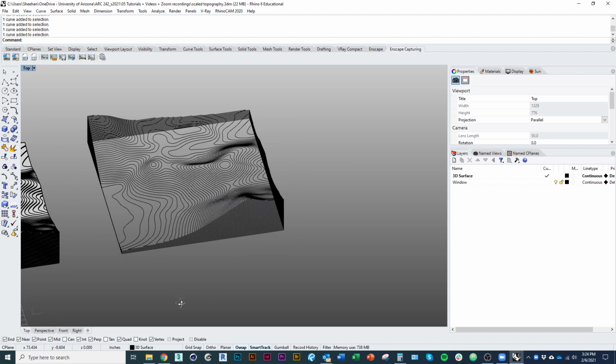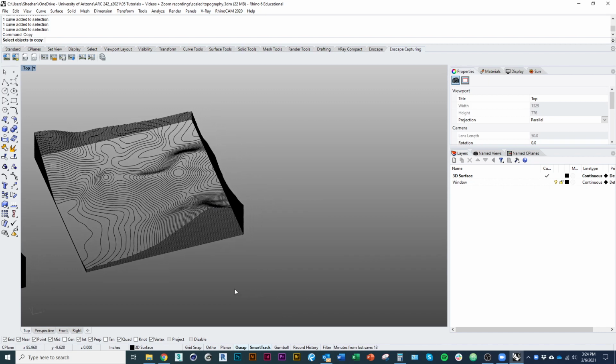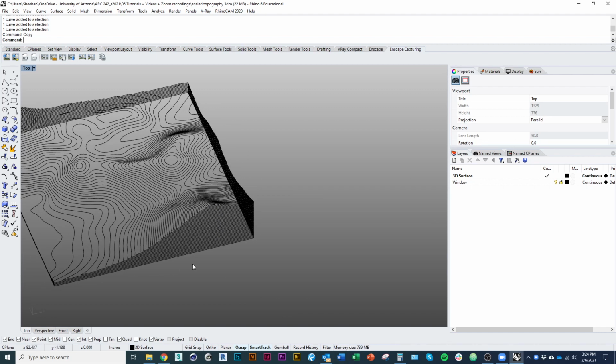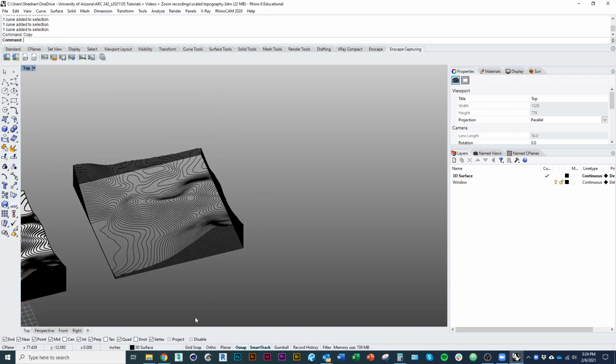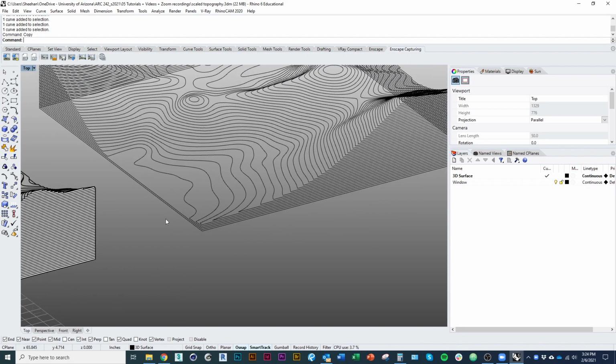So what I would actually have to do if I wanted to cut this is I'd have to take each piece and lay it out so I can position it on a piece of material and make a series of cut files for each of those pieces. And that means I have to actually move them all, right? Now there's an easy way to do this with a contoured model that'll save us a couple of steps.